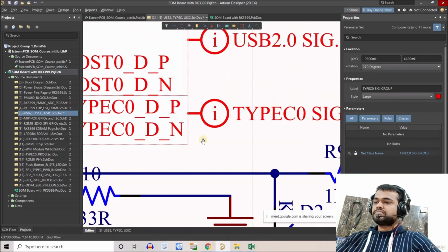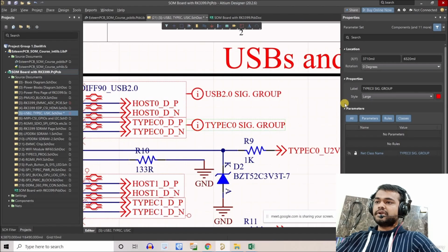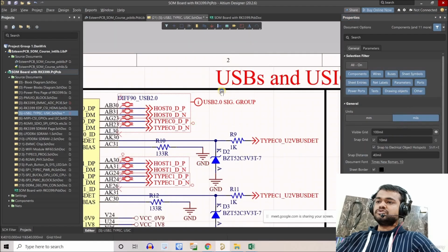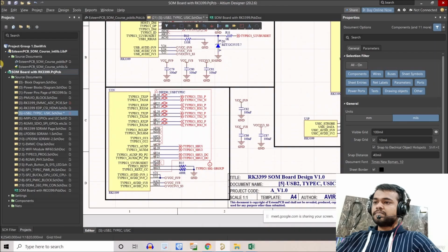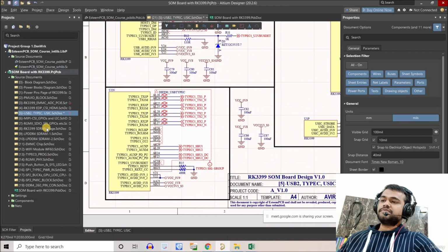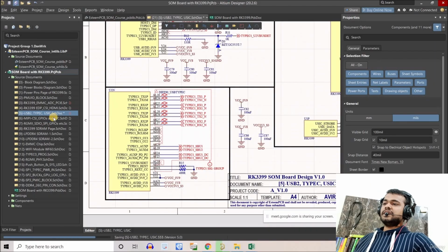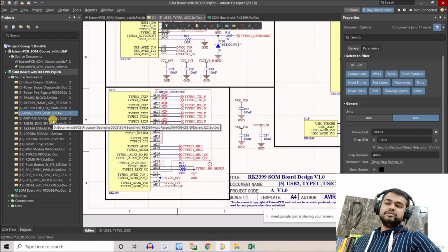Okay, and double click on this, and again it should be a tiny one. Okay, now save the project file. Similarly, I did the same thing for all the differential or single-ended connections where we have to match the characteristic impedance as per the design guidelines.